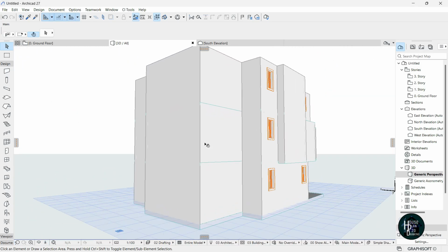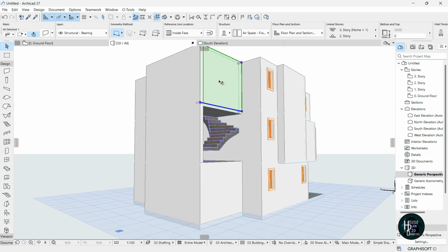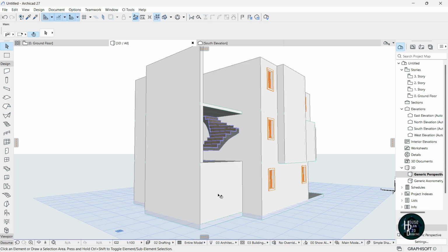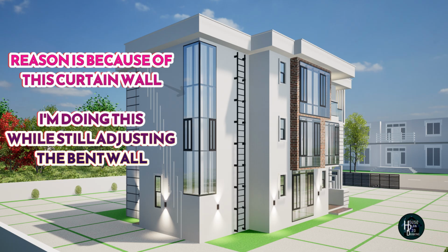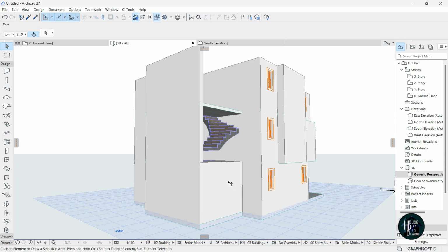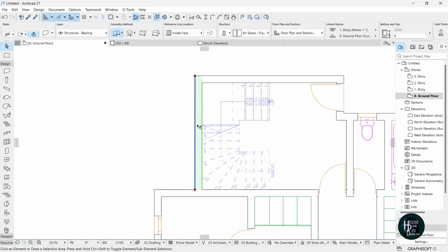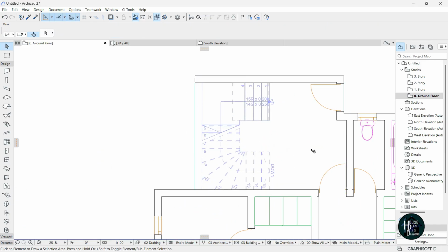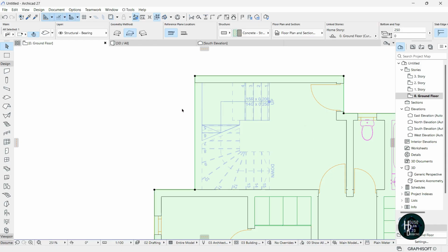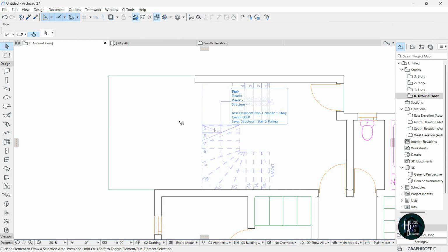Okay, now for this building, click on this wall, delete it. Click on this other wall and delete it also. You're going to be extending this wall to the upper side. We have to make sure this ground floor wall is very straight. Go to the ground floor plan, click on this wall and delete it. Now click on this white stuff to click on the slab, click this edge and move it outside like this. Okay, press escape on your keyboard.